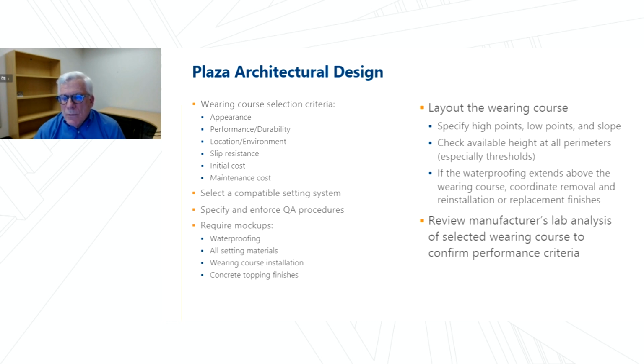You certainly want the underneath the wearing course or on top of the wearing course, you want the system to work with the waterproofing, not against it. And I think you want to review the manufacturer's lab analysis of some of those stone materials like we talked about earlier.